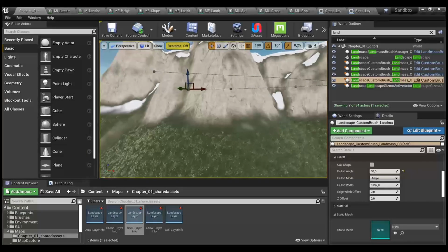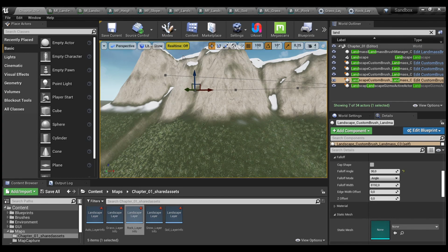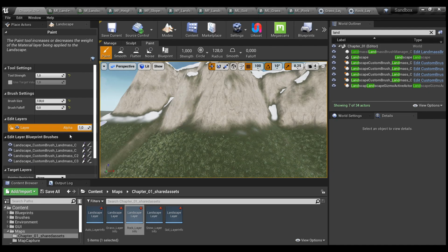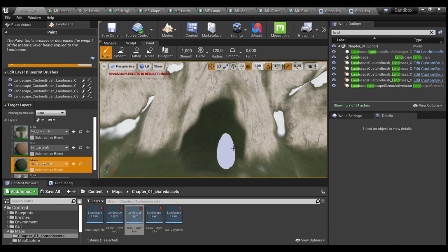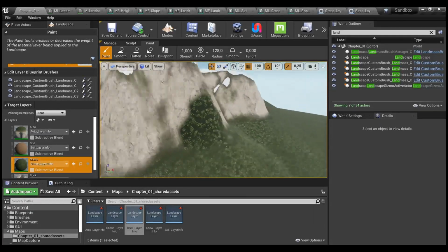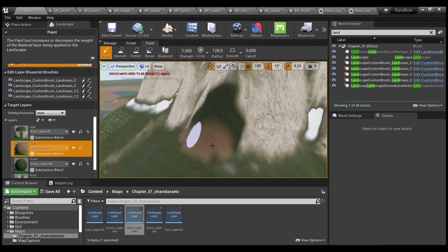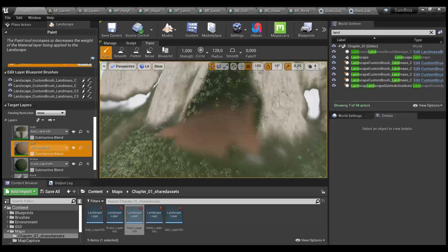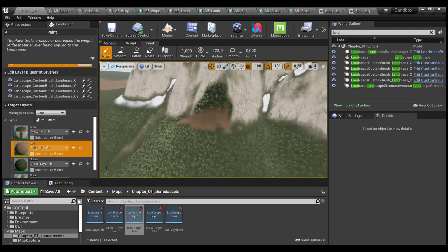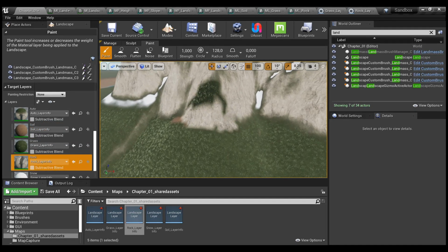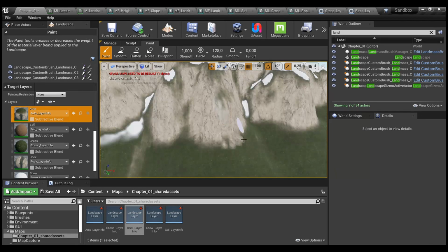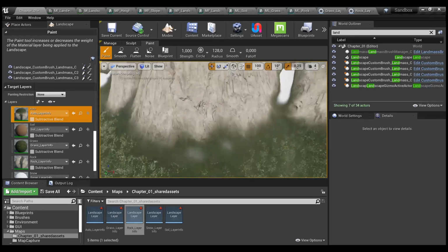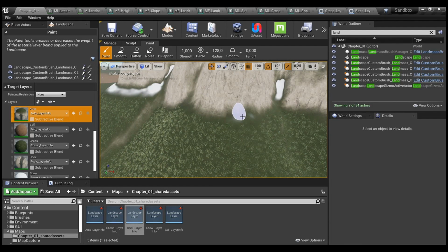And as I was saying, let's go quickly to paint mode. If I use the grass brush here, you can see we have grass applied to our slope. Now if we go with the soil, it will reduce our grass here, and in case you want to have it return to the default state, you can use the auto layer and just paint everything here. So now it's all restored to the first, unchanged state. That's how it works.